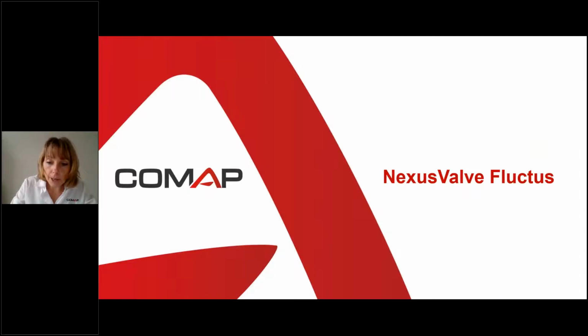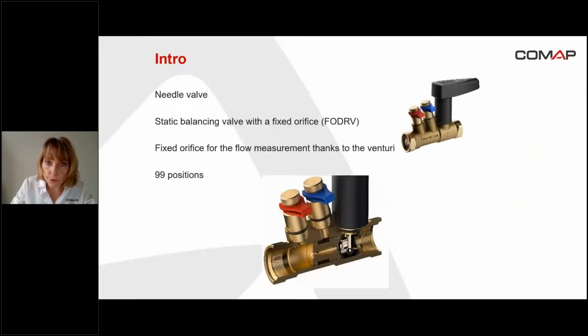Let's talk now about the NexusValve Fluctus. So first, it's a needle valve. You can see the needle here in order to adjust the flow. It's a static balancing valve with a fixed orifice, a double regulating valve.